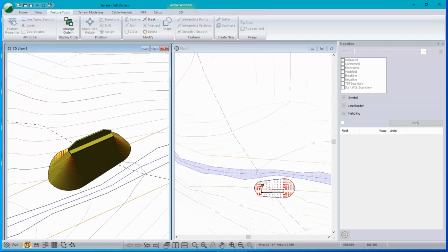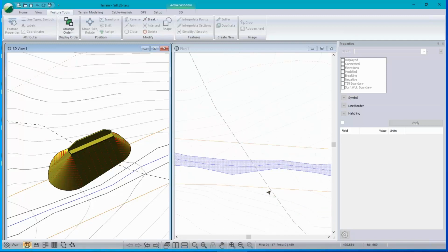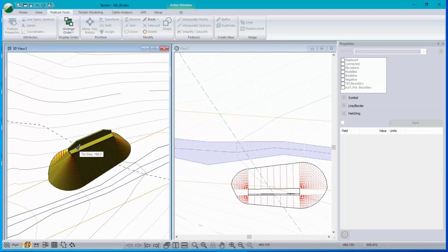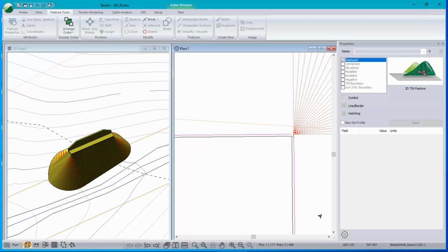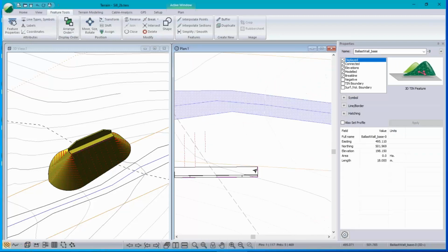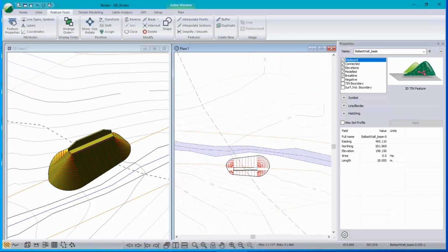So the beams are going to go across like this, whether they're logs or concrete or steel, and they're going to sit on the sill. So this is a concrete sill that I created and moved in here, and then I selected the bottom of it. There's the bottom, and I graded it out to create this little blob of fill that is kind of the first part of the bridge.